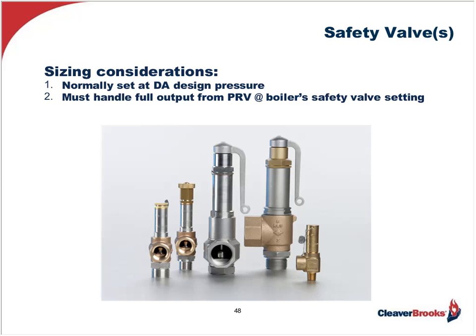It's all about additional safety because even though the deaerator is not fired, it's a boiler. They are still containing liquid under pressure with very high temperatures: 5 pounds, 227 degrees; 10 pounds, 240 degrees. Scalding. And if the vessel ruptures, it can cause very serious damage to property, life, and limb. And the safety valve is our last hope if this happens. Very important device.